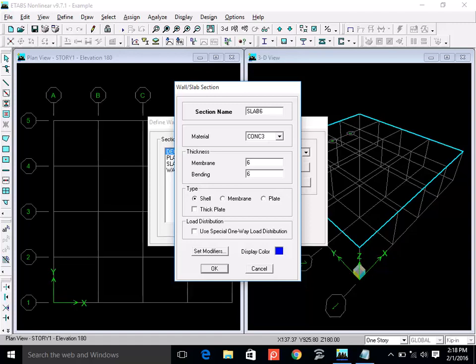It also resists shear force, right? So in theory and in real life, I should say, the slab should be modeled as shell. But generally, when your structures are large, these shell elements consume so much memory to solve that we do not model the slab as a shell element and do an approximation.